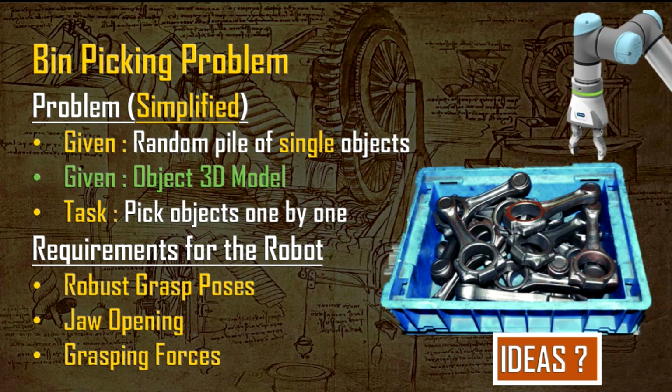Yes. And not just for identifying the depth of the objects, the depth information would give us the orientation of the object as well. Why? Because in the 2D perspective, it is very difficult to identify a 3D object in 3D space. If we have some depth information about the object itself, the robot can be moved towards that orientation, as well as the location of the object and how it is oriented. For example, if the object is lying 90 degrees, or maybe more than 45 degrees, it is very difficult to identify the orientation with just 2D images.